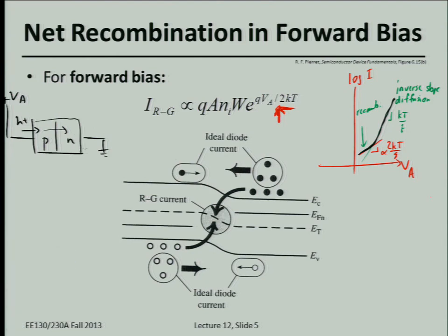Let's draw electrons diffusing across the junction, and some end up recombining in the depletion region. The metal contacts have to supply holes for diffusion into the N side, and electrons diffusing into the P side. But they also supply carriers to recombine at the junction. That's why this extra current to supply recombining carriers can become dominant at low voltages.